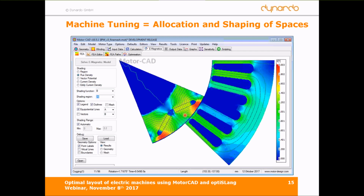If the field lines go around the winding, then if the coils generate their own field, we can generate torque. So this means this bridge should really become thin, because the flux leakage here, the shortcut paths, are undesired. But if it is infinitesimally thin, then of course it breaks. This chunk will break off due to centrifugal forces. So you can see a classic trade-off here, a classic design conflict. From the electromagnetic perspective, you would like to minimize this bridge. From the mechanical perspective, you would like to maximize this bridge, so you have to find a compromise.